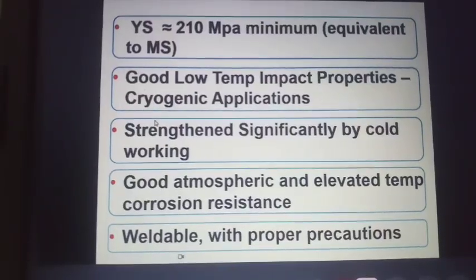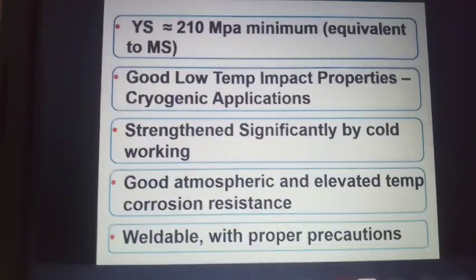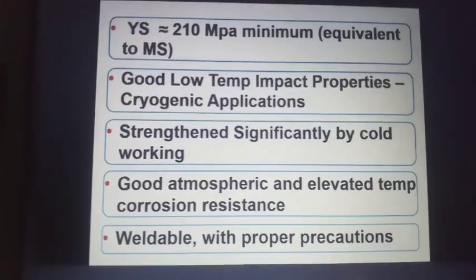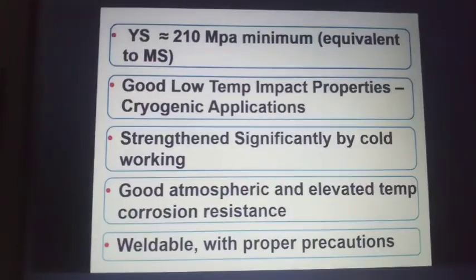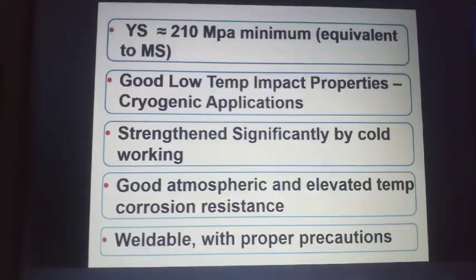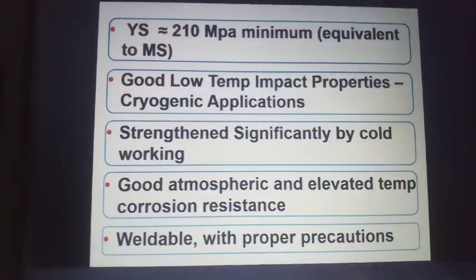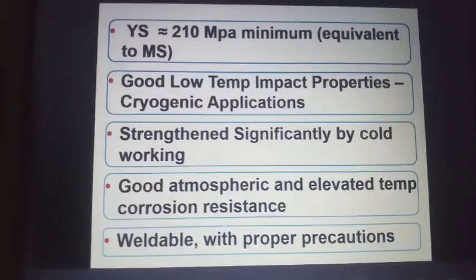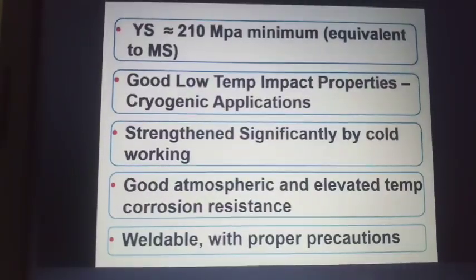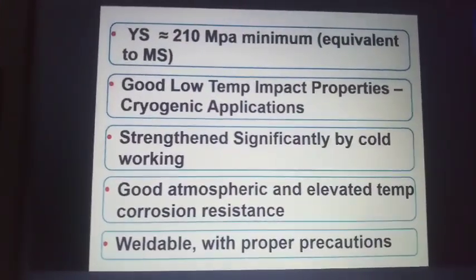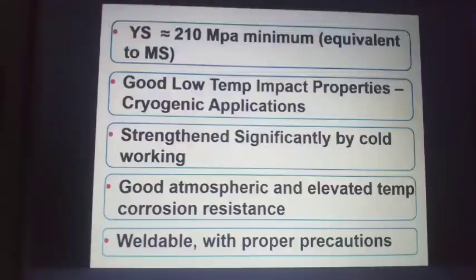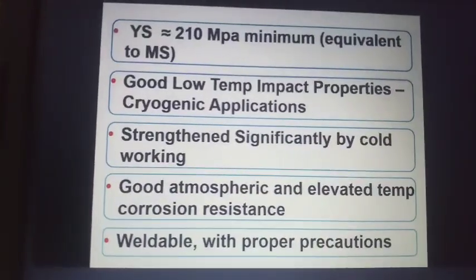Trustworthy. Even for austenitic, up to minus 110 or 111 only, impact testing is not required. Even minus 196? No, at minus 196, they will need impact testing. No, sir, up to minus 196, it is not required for 300 series, as per code. Some of the clients tell us to do testing at minus 196. Up to minus 110, they will say okay. But if it is directly minus 196, you go for impact testing.